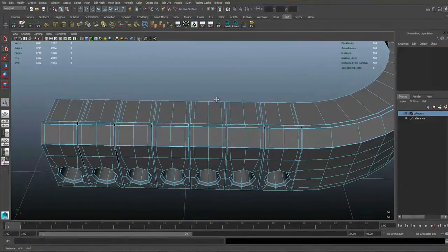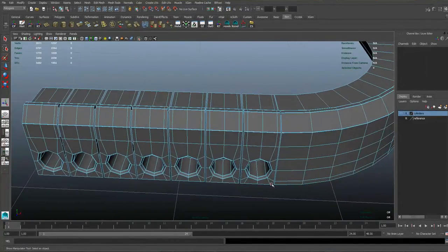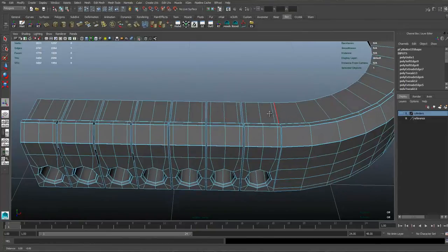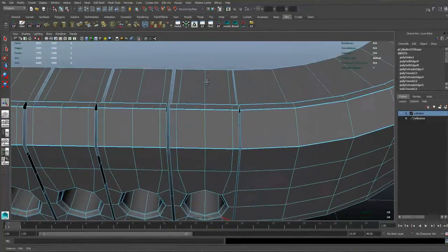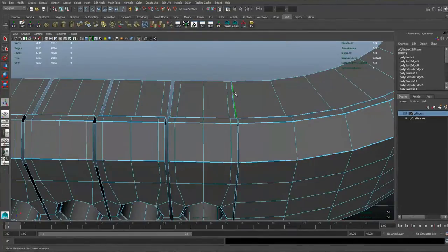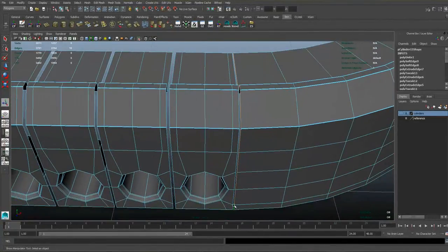So I'm now ready to go ahead and bridge this geometry here, remembering we can only do one section at a time. So I will start off by selecting the bottommost edge and then the topmost edge here, double clicking to connect all the way between them. Same for the opposite side. Click on the face at the top, shift, double click to the face at the bottom. It's important that you select equal numbers each time, and then go ahead and press bridge.